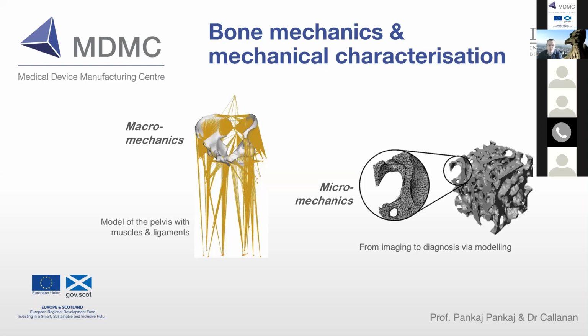To complement that, we also have a full set of mechanical characterization equipment. So the usual suspects: tensile testing, we can also do fatigue testing, nano indentation, and we have a rheometer as well. Nothing unusual about those, but the particular important thing there is we can also use them to look at biological structures and very soft materials. So we have load cells for our tensile tester that will be able to characterize very weak materials.